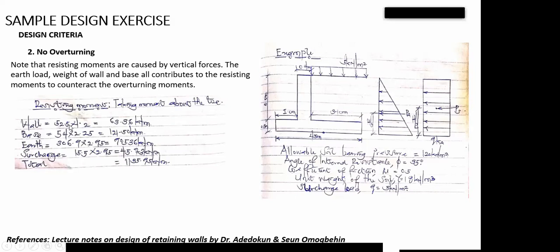Now, you have to be very careful. You've calculated your vertical forces each. So we've gotten the vertical force of our wall, and I said that the vertical force of our wall is going to be acting at the center. That is 0.2 of this wall. So if you are taking moment about this point, 1.0 plus 0.2, you're going to get 52.8 times 1.2.